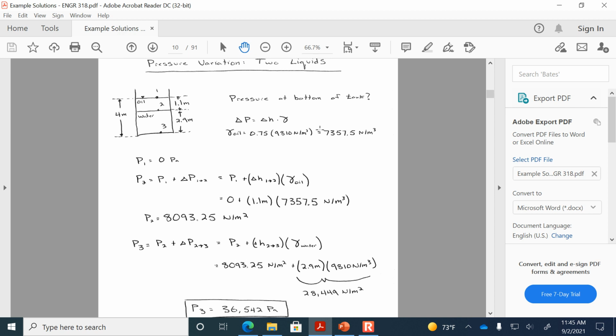And the strategy you should apply when you're solving the hydrostatic equation is start where you know something and work towards the unknown. Where we know something is here at the surface where it's in contact with air. What we know is that the pressure of the air and the liquid is the same at the interface.